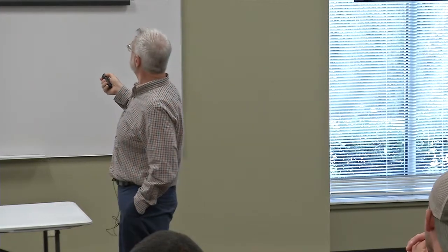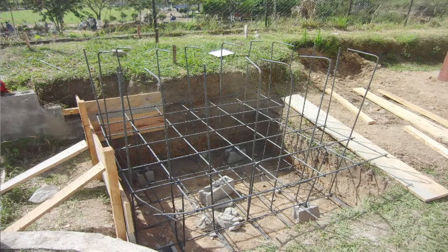This one we did have to form up. It was going to come out of the ground because it's got to get up above the edge of the hillside here because it's got to project across. So we raised this about 6 inches above what we expected to. The foundation was dug just a little bit too deep, and we also had to put the formwork there in place as well.